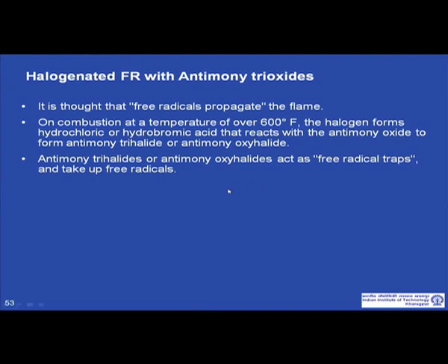It stops the thermo-oxidation processes which generate volatile, flammable organic compounds, and if they prevent formation of those compounds, they prevent the burning process. So, this is the mechanism by which halogenated FR along with antimony trioxide works synergistically.